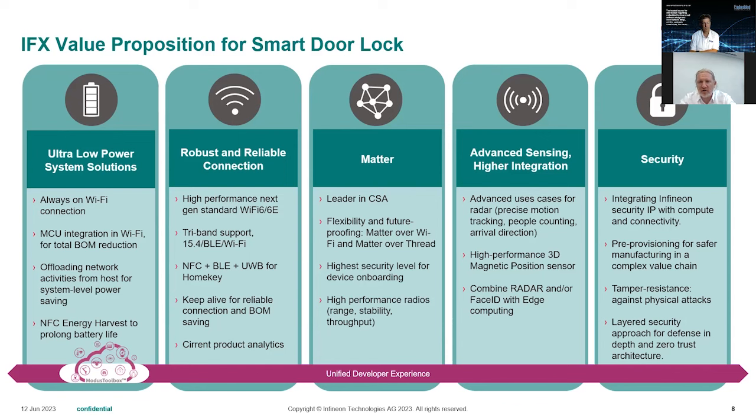So we have different radar sensors and time of flight sensors to really understand and only wake up when someone is coming towards the door, getting the door ready to accept a qualified access, as opposed to a PIR where your neighbor's cat walks in front of the door or somebody walking down the street also wakes it up, which is a complete drain on the battery life.